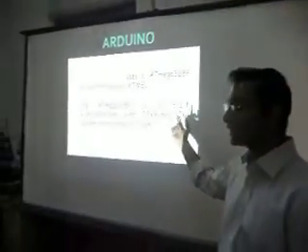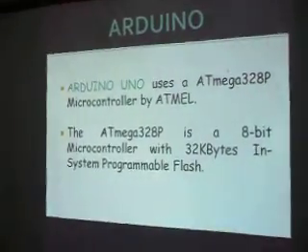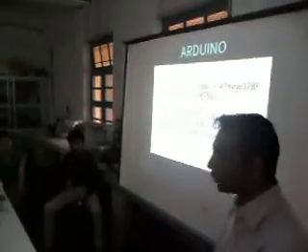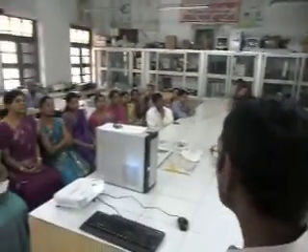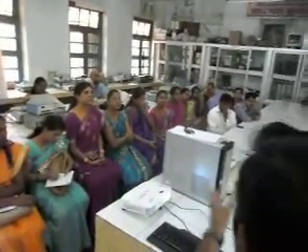So I guess everyone's familiar with the Atmel company. It uses a regular Atmel processor, microcontroller actually. Most Atmel chips require C language or rather a programmer, an AVR programmer. But a very good point about this board is you don't require a programmer. It's a built-in programmer. So in the board we can have a programmer as well as a developing prototype board. You don't have to have an extra board for accessing the pins or anything. Once you program, you can use the same board.